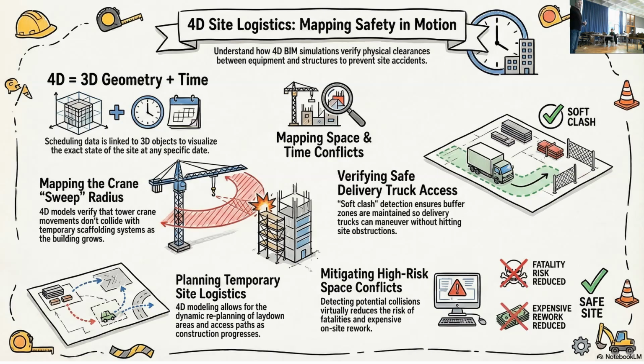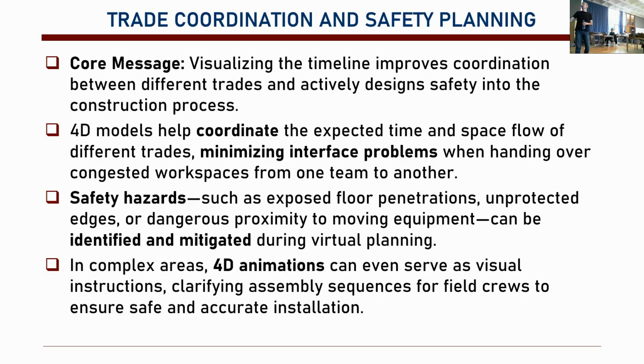They have their own scanning labels, etc. And then the 4th floor windows arrive to the site in the morning of that day, because you don't have space on site for the windows. So it's delivered in the morning, and that day those windows are put in place. So just-in-time delivery for construction works great in congested city areas. Okay? And of course, trade coordination, safety planning.